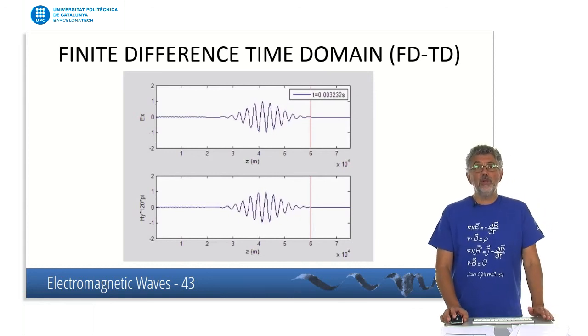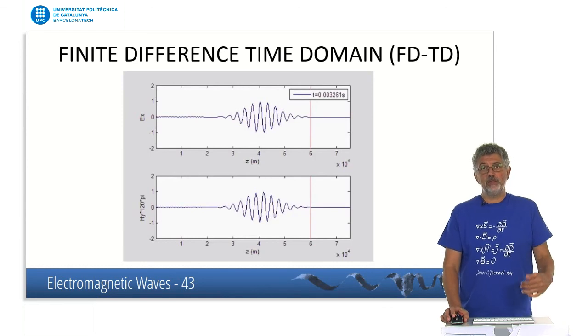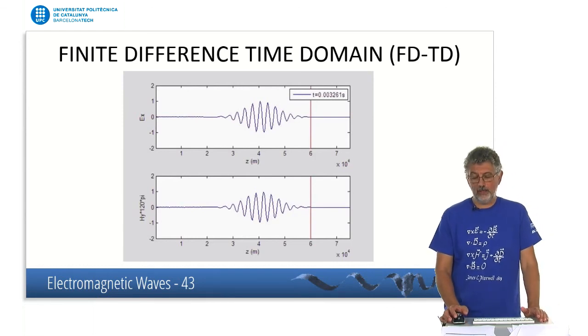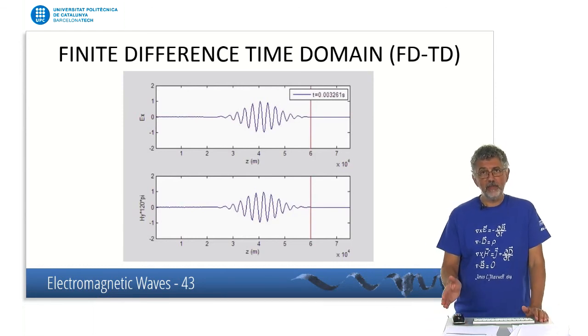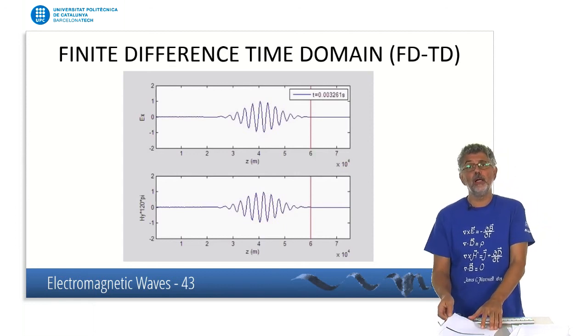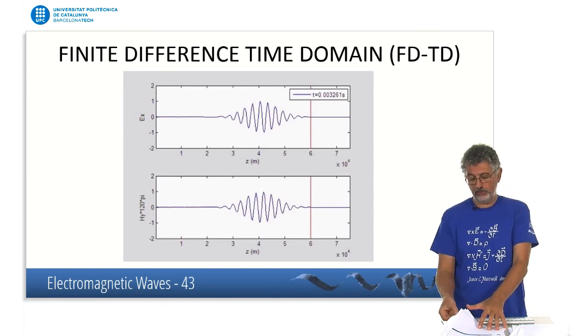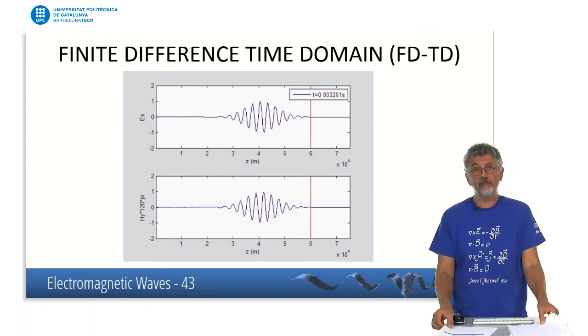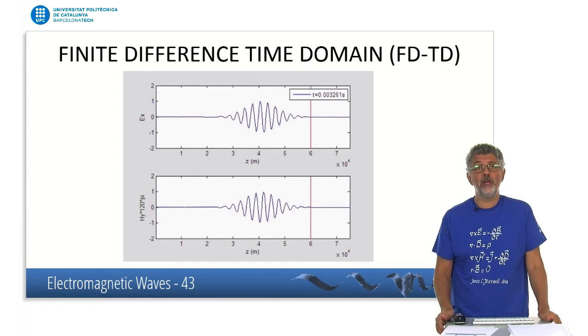And notice, we have not done any math. We have just taken the algorithm, we have placed the boundary condition, which is the value of the electric field in that position, which we know has to be 0, and we have obtained the numerical solution for that.